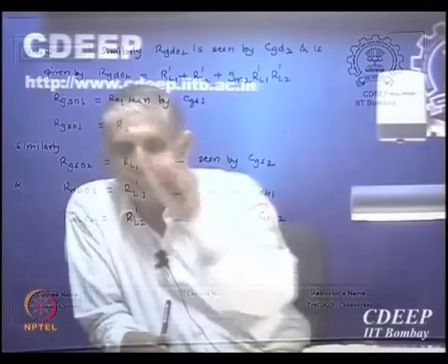See, for each of these, only when the gm terms on the V other terms occur will you get this longer expression, otherwise only simple resistances will appear. Only in those cases will you get RL plus RS plus gm RL RS kind of term; the rest of the time it is straightforward. So I calculate all equivalent resistances seen by the capacitances, and so I can calculate 6 time constants. Is that clear? RC, RC, RC for all of them. Is that okay?